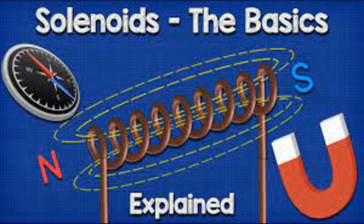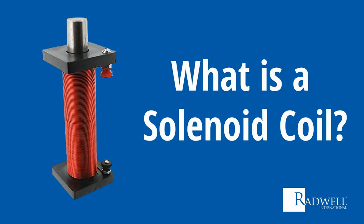1. Linear solenoids. Description: these solenoids produce linear, straight line motion when activated. Operation: when the coil is energized, the core or plunger moves in a straight line, either pulling or pushing depending on the design. Applications: widely used in applications that require direct mechanical action, such as electromechanical locks, automotive door locks, vending machines, valve actuators. Types of linear solenoids.